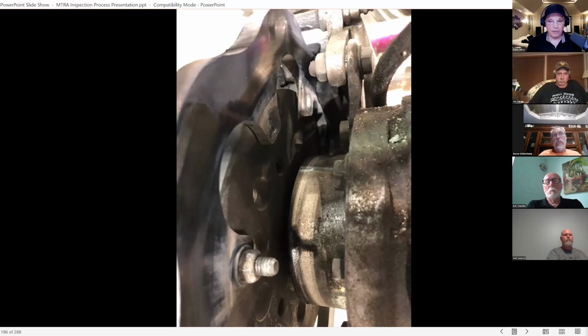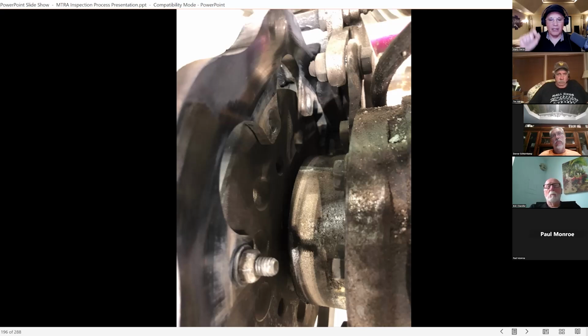A big area of concern when you're doing your inspections is checking the bolts that hold a rotor to the flange. You want to make sure that they're using prevailing torque nuts, that they're not nylocks. Those things get red hot. The brakes get red hot all the time, and the nylon melts right out of them. And then they're useless. So they need to be those nuts that look like they're crushed, called prevailing torque nuts. They're a pain in the ass to work with. They're hard to get back off once you put them on, but you don't want those things backing off.